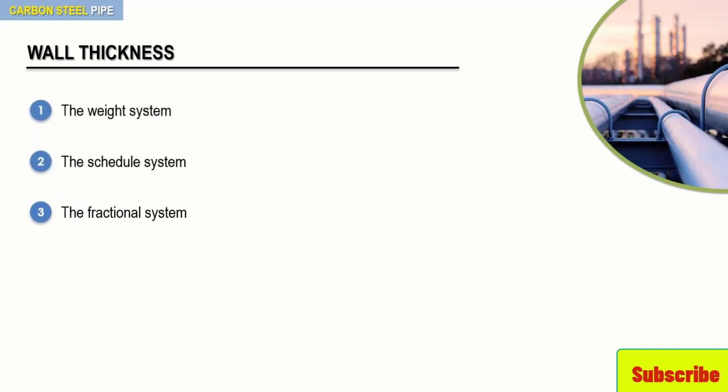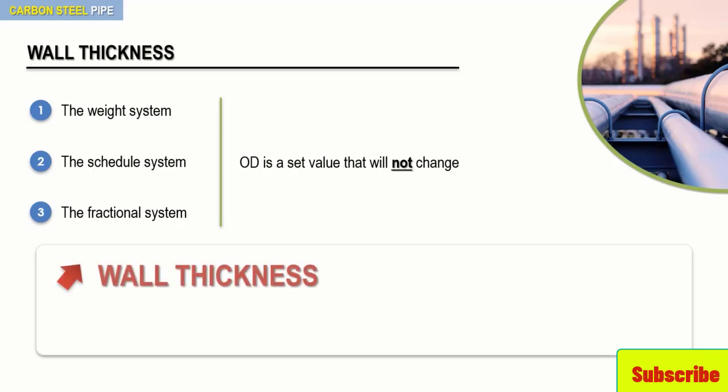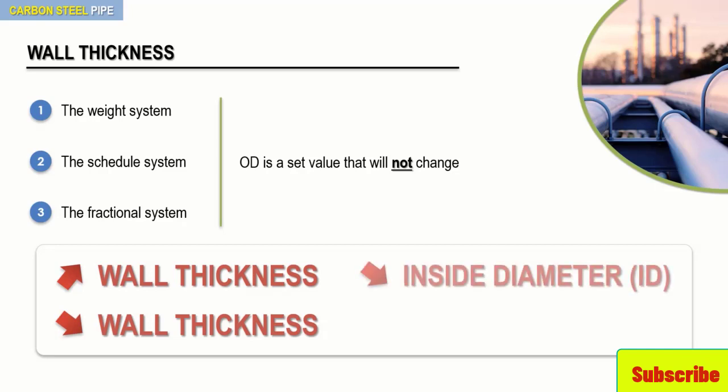Okay, at this stage, keep in mind, no matter which method is used to categorize a pipe's wall thickness, it will not affect the outside diameter. Why is that? Because the outside diameter is a set value that will not change. As a result, as wall thickness increases or decreases, it is the inside diameter that adjusts.